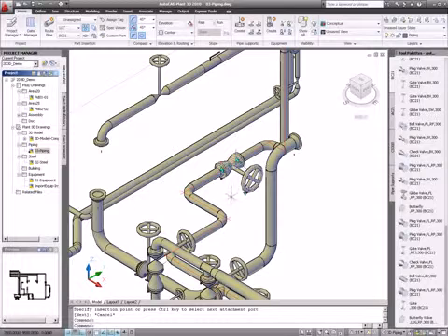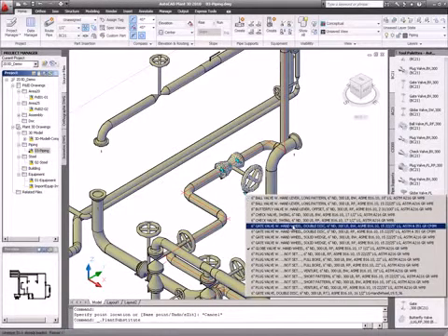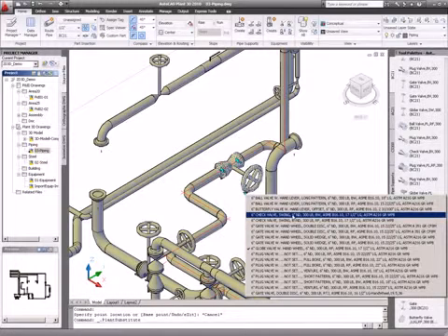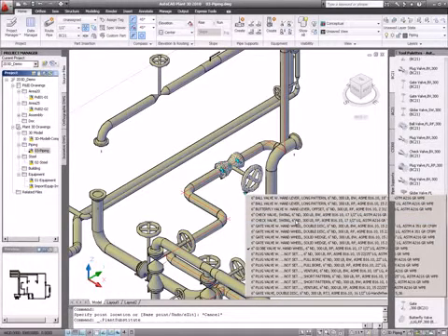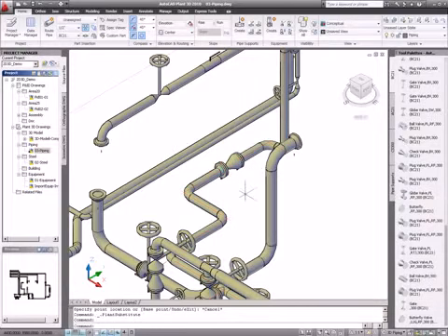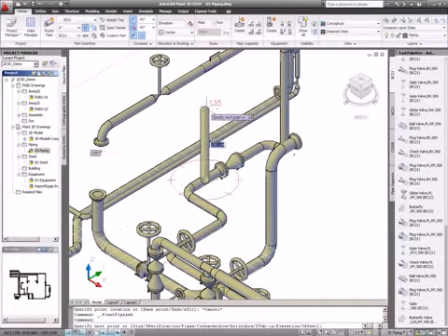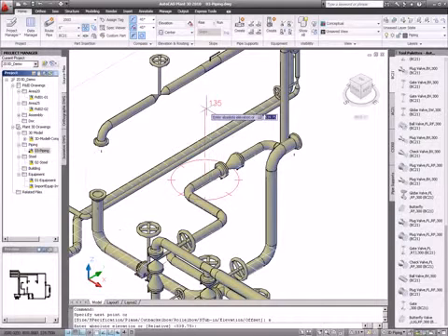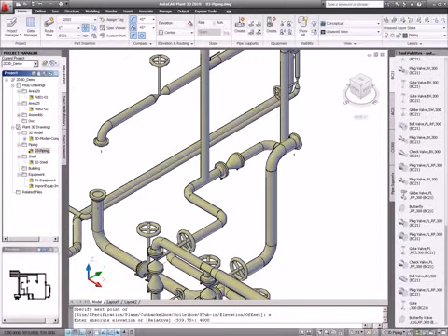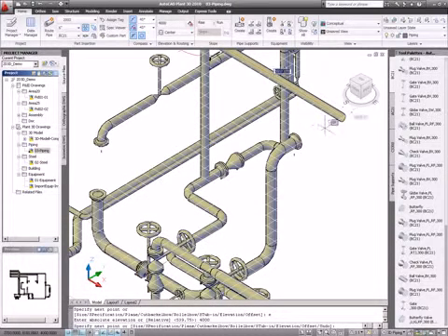You can actually click on it and then you can replace the valve with the selected substitute part, and then you can select and change it to, let's say, a check valve. That should be a flanged one, and it changes it for you. And if you want to go with another pipe, I just select the pipe and see the plus sign, start with the pipe and give it elevation to a new elevation, and then you can keep on with the pipe. So that's the basic thing with the pipe.